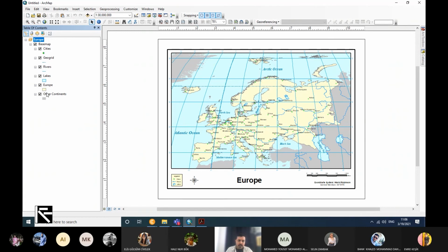We have three important entities under our layer. We have a polygon, which is shown by a rectangle, as you can see. We have a line or polyline, and we have a point or node. These are our entities. Sometimes we have a vector entity, sometimes we have a raster entity, but at the moment these are vector entities. So this is about the table of contents. You can change the table of contents appearance based on the data source or the visible layer. These are different methods of table of contents, but I typically use the first or second one, depending on the project.